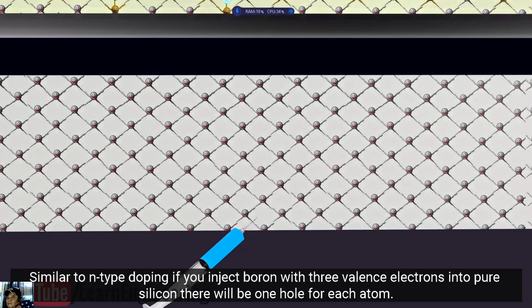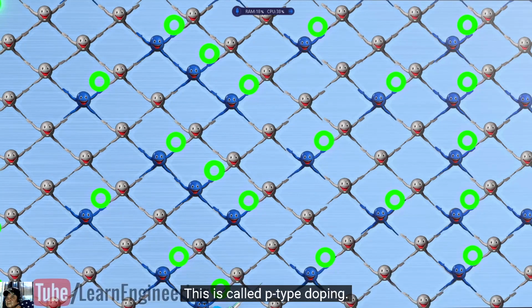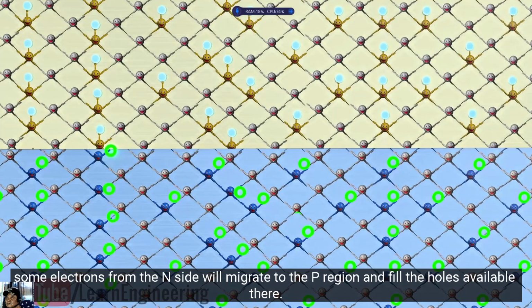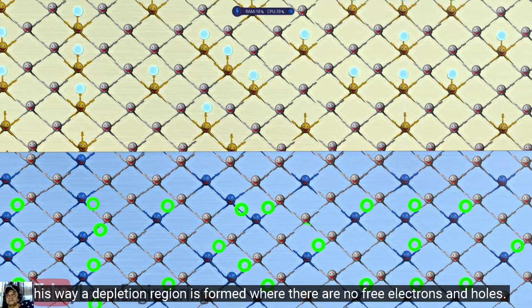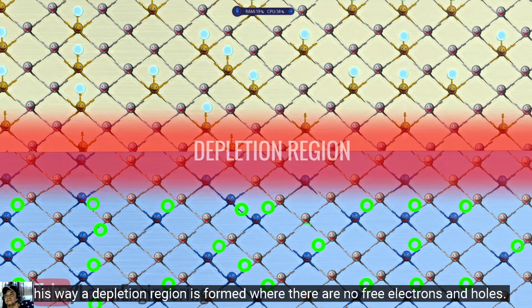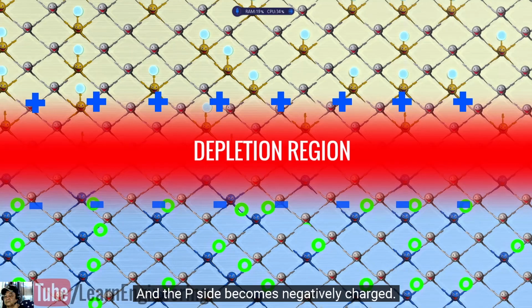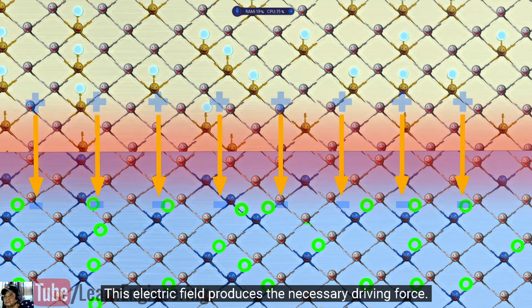Similar to n-type doping, if you inject boron with 3 valence electrons into pure silicon, there will be 1 hole for each atom. This is called p-type doping. If these two kinds of doped materials join together, some electrons from the n side will migrate to the p region and fill the holes available there. This way, a depletion region is formed, where there are no free electrons and holes. Due to the electron migration, the n side boundary becomes slightly positively charged, and the p side becomes negatively charged. An electric field will definitely be formed between these charges. This electric field produces the necessary driving force.